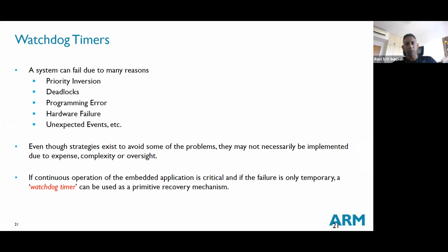Those of you who use Windows know the blue screen, correct? Or on your handphone, sometimes it suddenly hangs, and then after a while it reboots. When it hangs and nothing works, you can't press the button, then suddenly it reboots by itself. That is where the watchdog timer comes in.